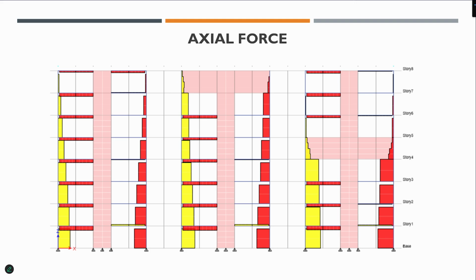Okay. So you can see this idea that below the outriggers you get this very large force is the key to the behavior. So now what we can do is optimize the structure: we can increase the column size here further and reduce the column size above. So it will also be economical because we don't need the columns above to be so big. So these columns are normally becoming larger, which are at the end of the outrigger. Okay. So that's the axial force thing.